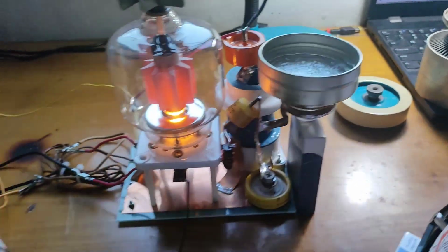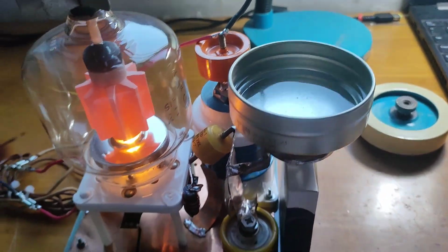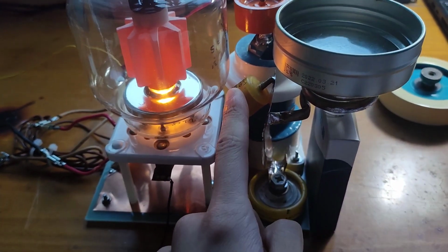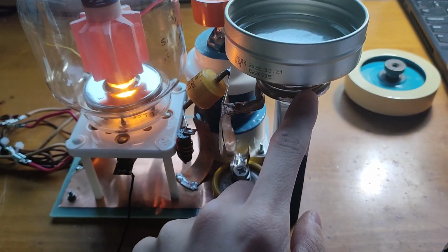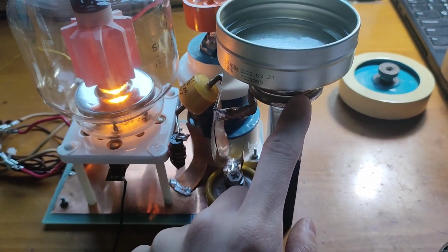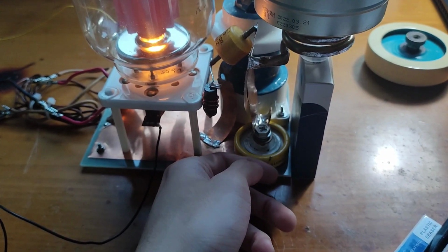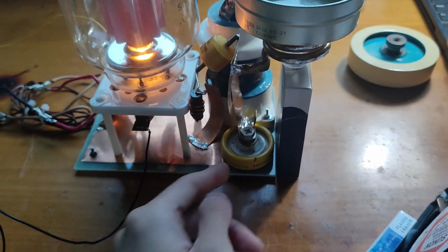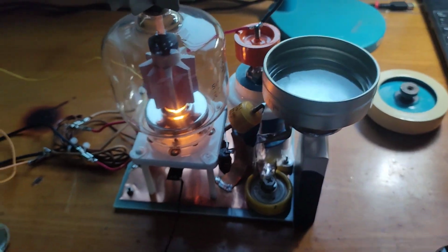Okay, now the water is boiling, and we see that the grid current is a bit less than just now. Also, the cathode current is a bit less than 400 milliamps. Okay, now let's stop the test, and the water is still quite hot. We can touch this feedback capacitor, which is a bit hot. The resonant coil, I guess it's around 70 to 80 degrees, and the resonant capacitor in the voltage divider setup is a bit warm, and this very large capacitor is also around 40 degrees now.